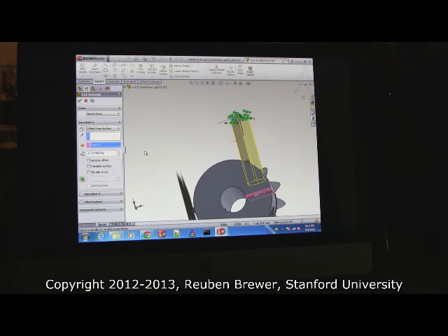Okay, when this happens, now just mark it. If anyone's turns all bright yellow in the sketch and says it's over constrained, it means you added some point that you shouldn't have. Try clicking one of the little point things and hitting delete, and as just happened, it'll go away. Is everybody where I am?